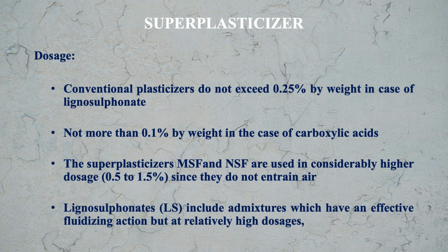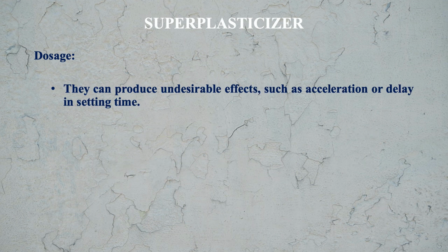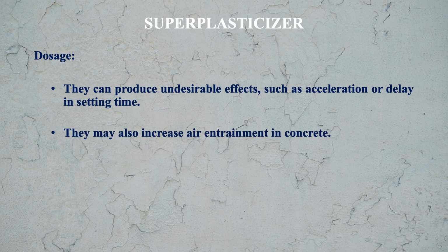Lignosulfonates include admixtures which have an effective fluidizing action but at relatively high doses. They can produce undesirable effects such as acceleration or delay in setting time. So we have to be very cautious while using these. They may also increase air entrainment in the concrete.